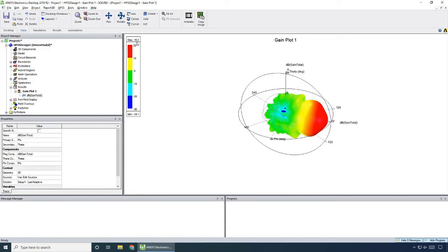And essentially what that means is that that's how much gain we're going to get relative to an antenna that senses equally in all directions, because the antenna can't actually make a signal more powerful, but it can be more directive, allowing us to receive more power from a certain direction. So it's always a trade-off in that way. And so this 16 decibels,